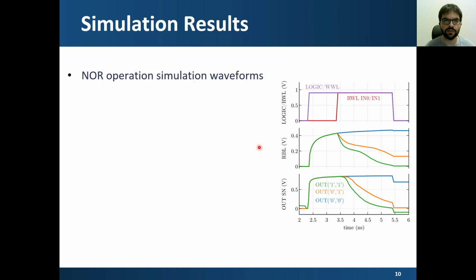We evaluate the performance of the logic operations in simulations. Here we have the waveforms for the NOR operation simulation. We can see here how the operation is performed. First, both the write word line of the output and the logic line are raised, and this charges the read bit line and the output storage node to an initial value.